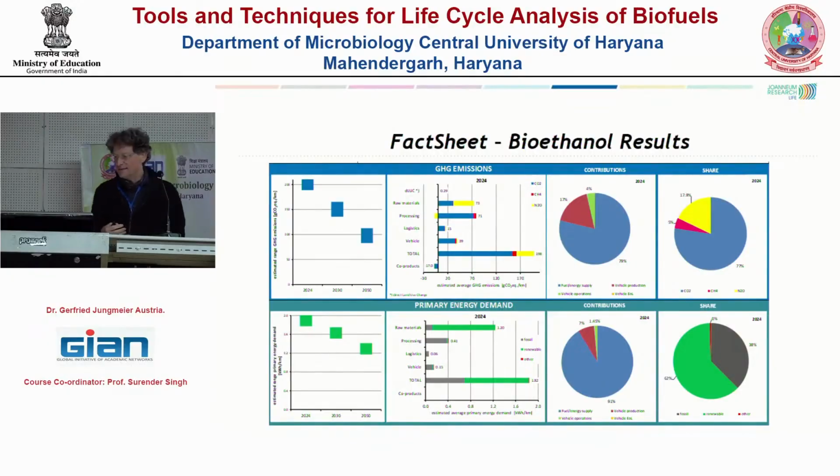Yeah, and additionally, the red one is the emissions from the vehicle production. So we have split it here into the supply of the fuel to the vehicle and the vehicle production, and the green one is the vehicle operation. So you see the vehicle production here roughly has 15 to 20%, which is really only the vehicle production. And this green part, as the ethanol combustion is so-called CO2 free, is counted as zero.